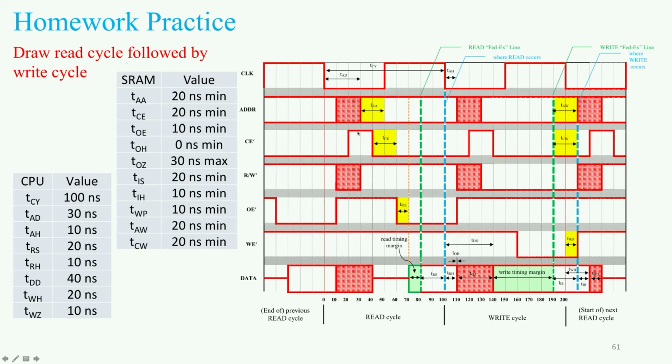The chip enable bit flips to a potentially high state here because it corresponds to this period where the crosshatch occurs for the address, meaning that the address is in an unknown state, so the chip enable bit could be flipped off. For all of these simple examples, we're assuming that when the address goes to an unknown state, chip enable is going to be off. If you drew this as a crosshatch, that's also technically valid, but it's maybe simpler to think about it as turning off. And that stays high for 20 nanoseconds because the address is unknown for 20 nanoseconds. This cell corresponds to this cell in the chip enable, and this cell corresponds to this cell in the chip enable. Finally the address gets itself figured out here, so now it's valid from the CPU. Ignore the yellow stuff for now. And that state is reflected in the chip enable bit 10 nanoseconds later because of the delay. So the chip enable is always 10 nanoseconds behind the address, which is why this is effectively just shifted over.